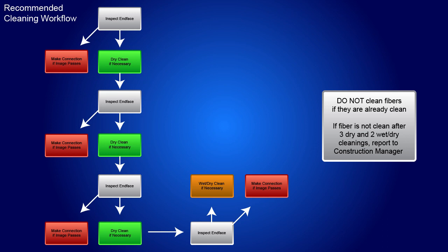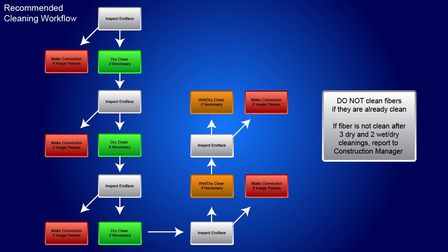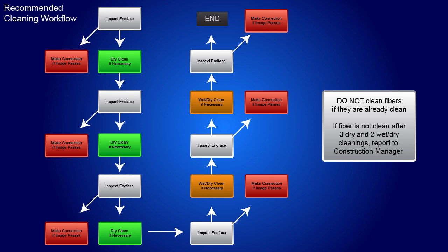Inspect after performing the wet dry cleaning, then make the connection or perform another wet dry cleaning. If the fiber end face is determined to be acceptable, make the connection. If not, the end face can be reported as fail and can be escalated through the appropriate channels.